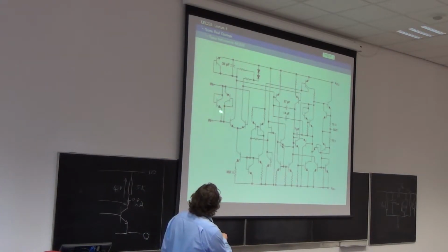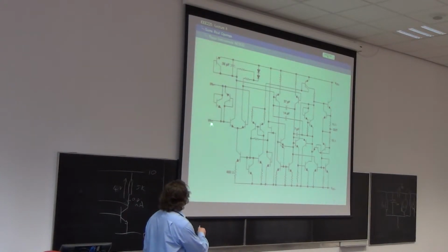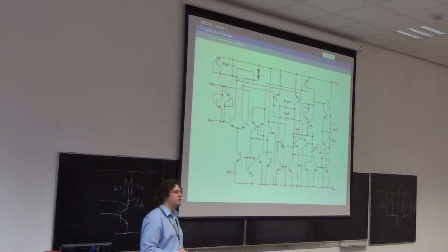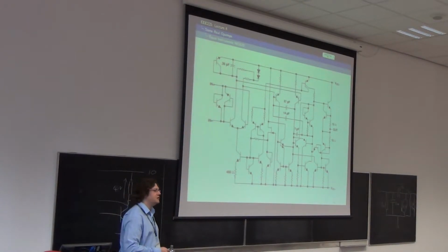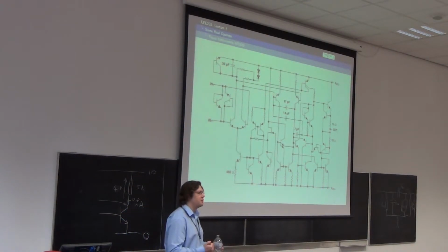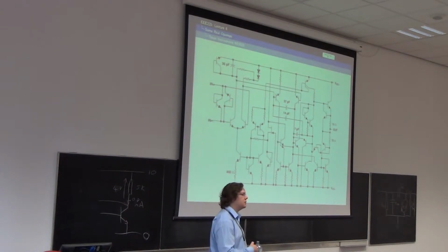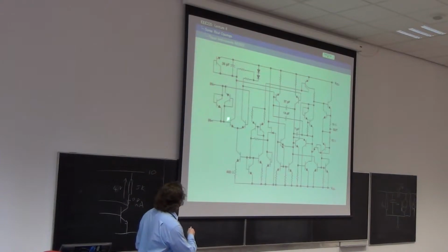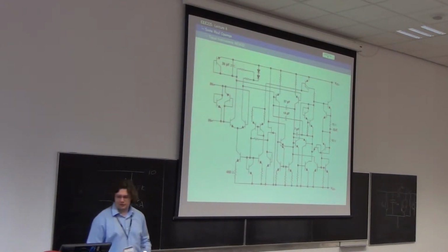There is. These two transistors are made up to look like diodes, and if you put more than 0.7 volts between V plus and V minus, you'll end up in a situation where one of those diodes conducts. Now the best way to blow up an op amp is to force its inputs apart and try and give it some feedback, so you'll drive a large current in, and these diodes will turn on to prevent the destruction of these transistors. Well spotted.